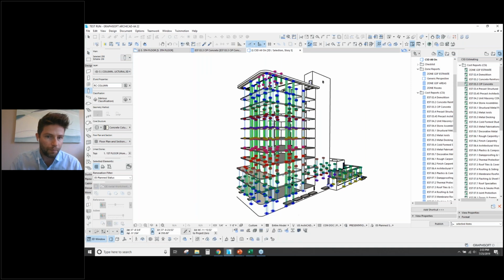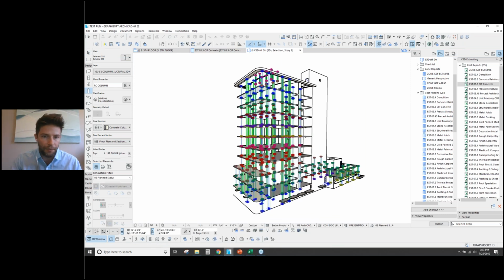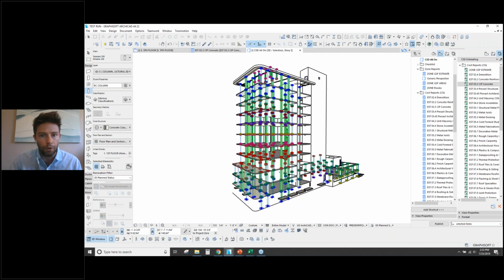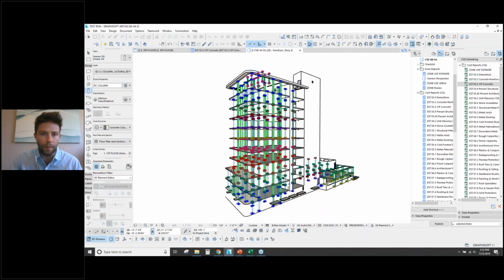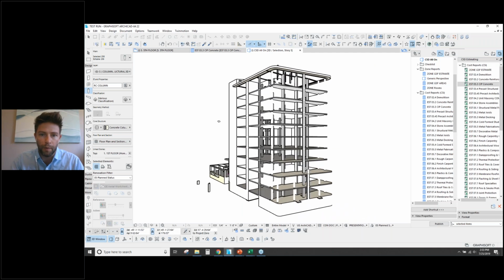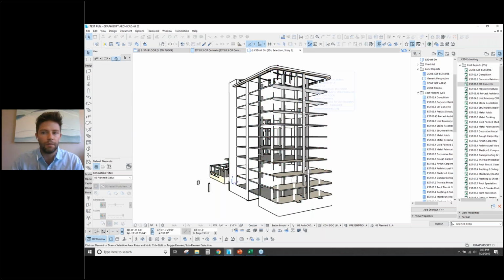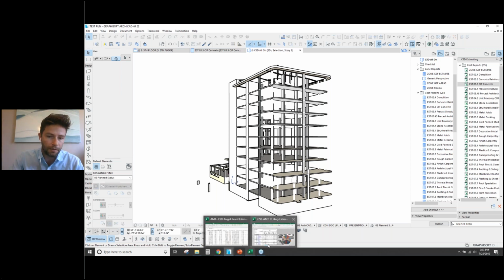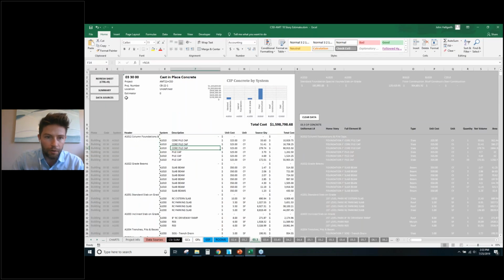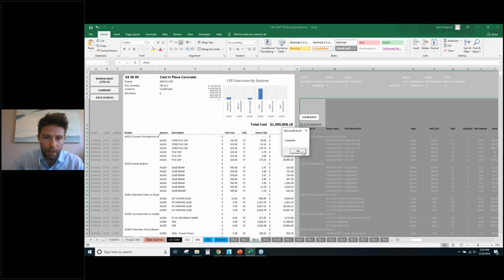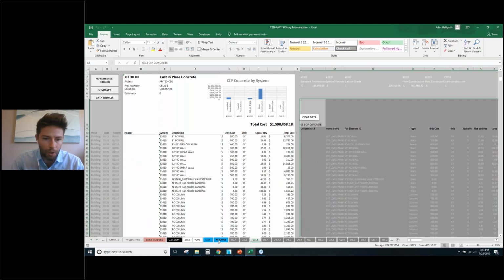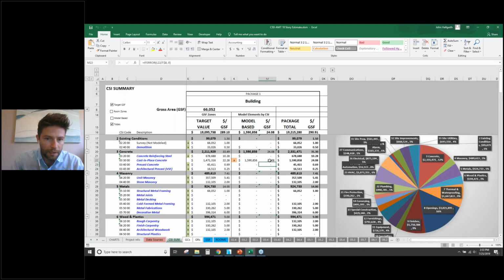And obviously, if you were working with a contractor and they were doing their own takeoffs, if they could leverage your own quantity reports and work together in a collaborative manner, then you can see how this can be a real time saver so that you don't have to go through and make updates all the time, even as the design's changing. So we could go back now and let's just refresh this. And just by adjusting that $50 per cubic yard, we can see that lowered it just a little bit for us, but maybe we need to look at other places for shaving off more cost.